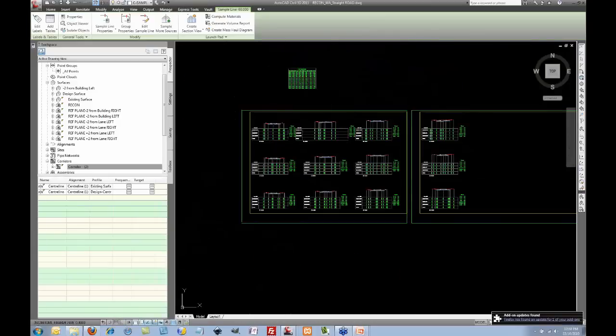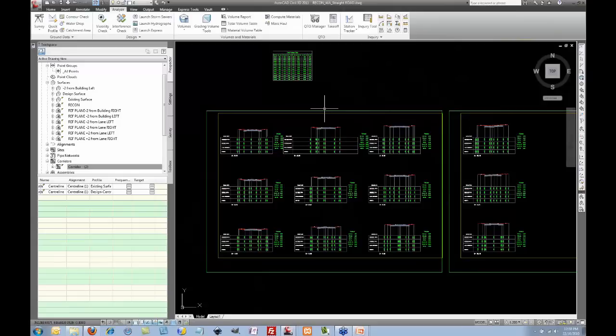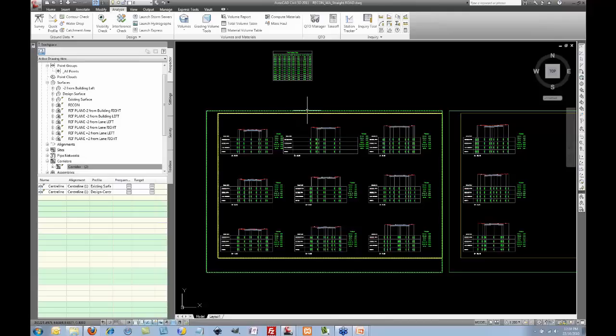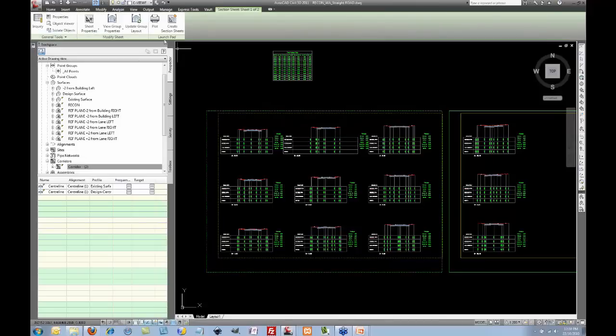So what's happened here is up on our plan view, up on our section view, chainage 60, where the mouse is now, is starting to encroach on its two neighbors. So all you do is select these guideline sheets, these green and yellows, and you'll see a button on the ribbon called Update Group Layout. So you press that,